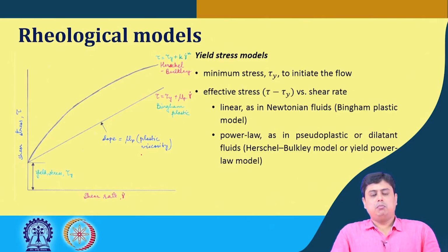Apart from the power law, there are other rheological models available for non-Newtonian fluids, and one such set of models is the yield stress models. In such liquids, you need to apply a minimum stress in order to initiate the flow.